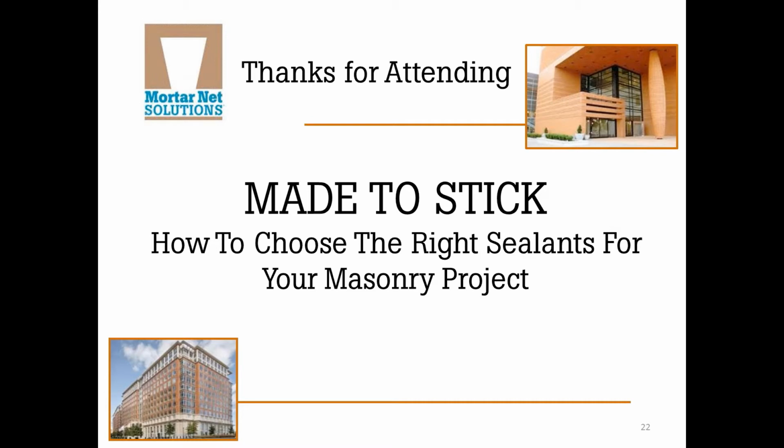But if you have a backer rod that is not a bond breaker, in other words, if the sealant sticks to the backer rod as well as the two pieces of material that it's attached to, that's when you get that cohesion failure that I mentioned. So you want to be sure to use backer rods that the sealant will not stick to.